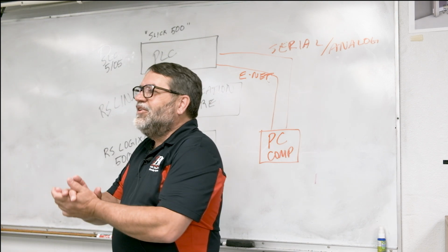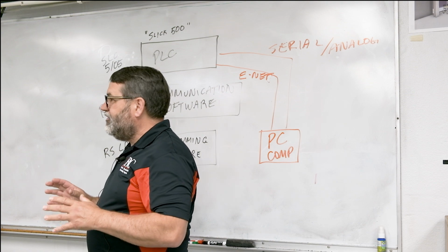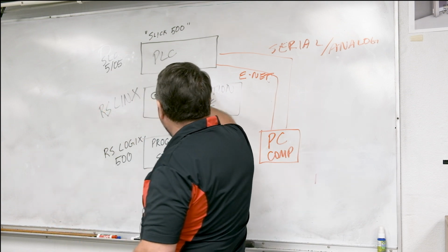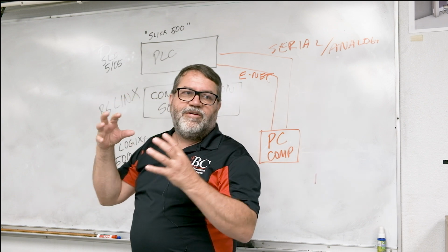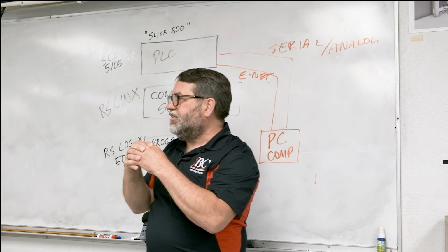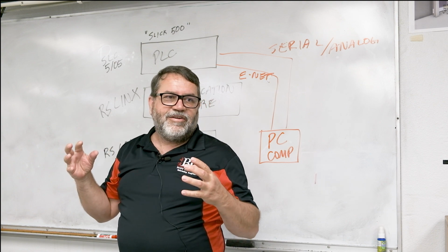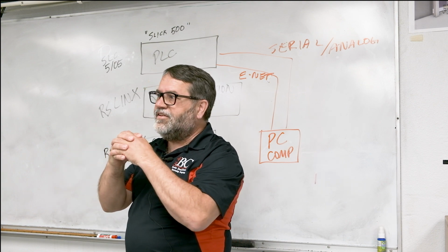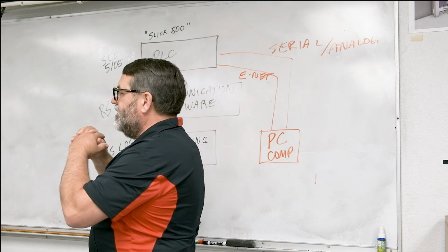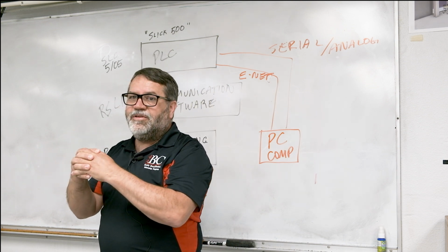Closer. So when you establish communication between RSLinx and the PLC, it makes a very robust connection. It's hard to get that connection sometimes, you got to try a few times, but once it makes that connection, it doesn't want to let go. It says, okay, I got it, I'm not letting go.